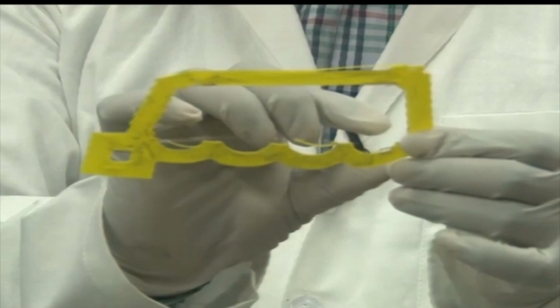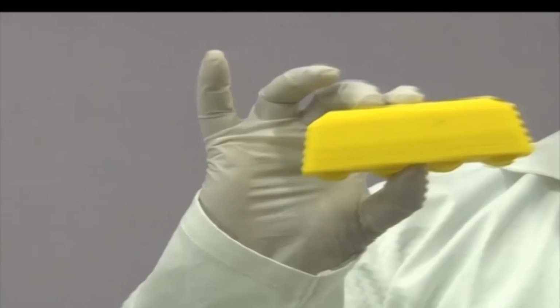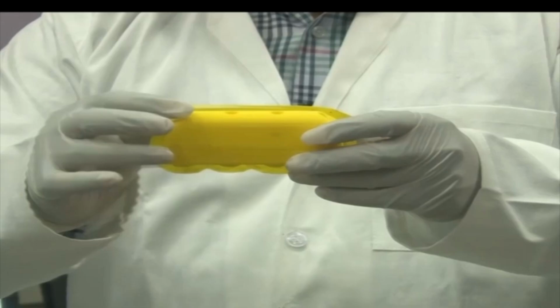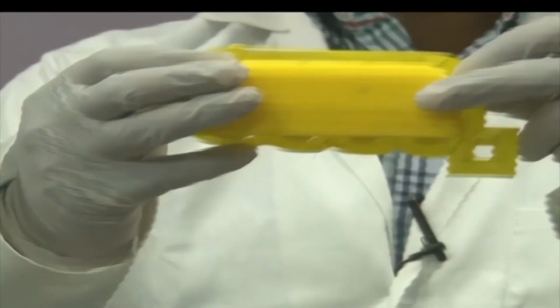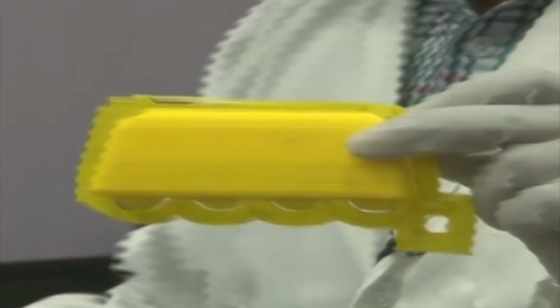So we are talking about the selection of brim here in the software. When the nozzle head starts printing, it prints the actual model that we want to print, but it will deposit a little extra material to produce this first layer. This is actually the brim. This is the model that we have. This is the model that is produced. So it will deposit a little more material. This extra material is brim.